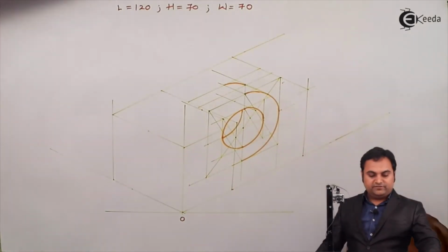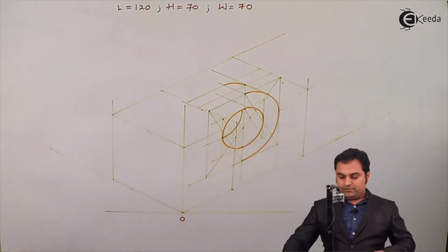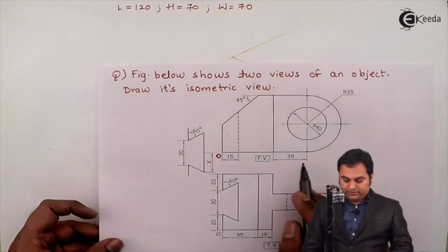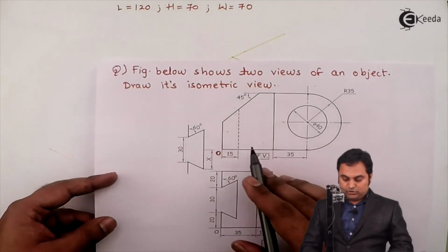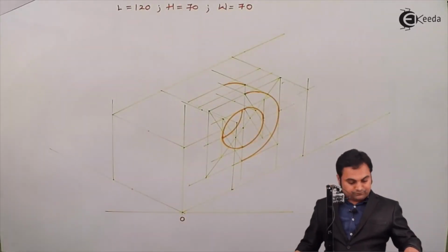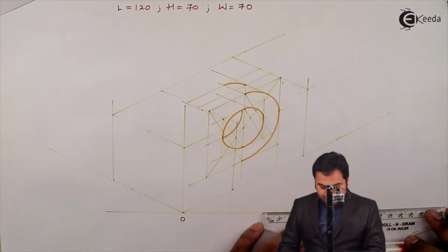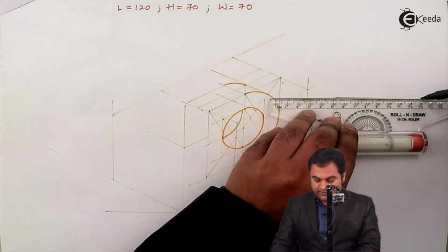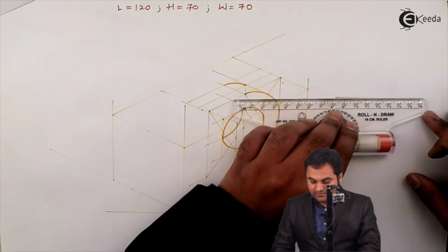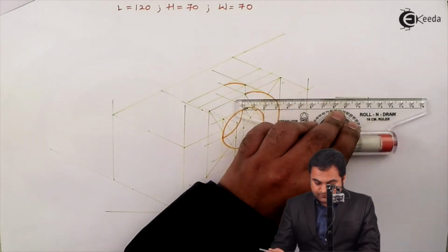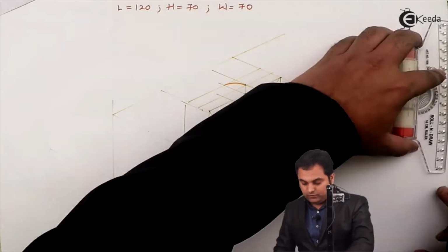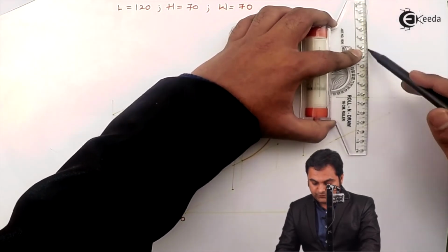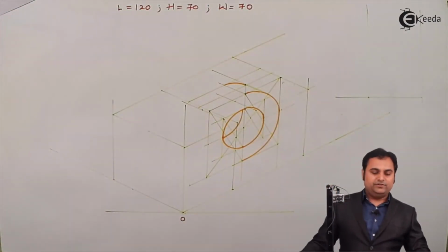For that, here I'll draw a rough diagram of the same figure, which is leaving this 70 mm, whatever is left, that is 50 mm, is this block. So the length of the block is 50. I am drawing it somewhere here, or even at the top, it would be fine. Drawing a light line, marking the length of 50 mm over it. Next, vertical lines through these points, vertical lines. This procedure we have to adopt if we have an angle in the drawing.